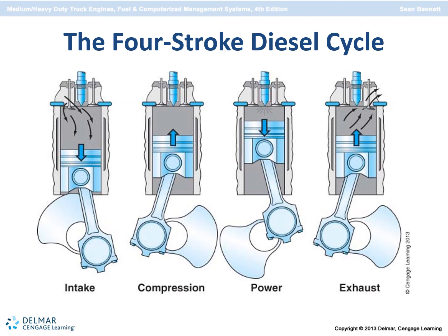On our intake stroke, the intake valve is open, allowing boosted intake air to get into the cylinder, and it travels to bottom dead center. On the compression stroke, the intake valve is closed, the exhaust valve is closed, and the air is compressed to build temperature.